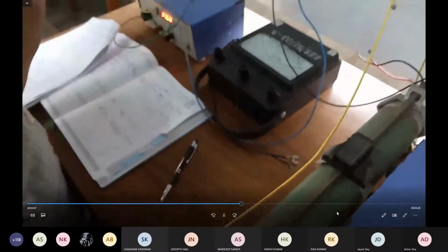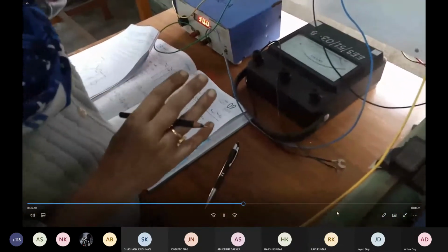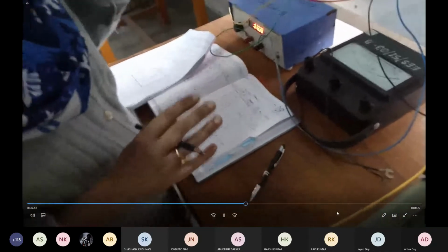So this is a 100 ohm resistor. Now let me show you the ammeter reading as well as the voltmeter reading. So this is noted down, for which we can calculate the RL, how? VL by IL. Next, our requirement is to have the V Thevenin or V open circuit when the load is being removed, and when the load is zero, that is the short circuit current.